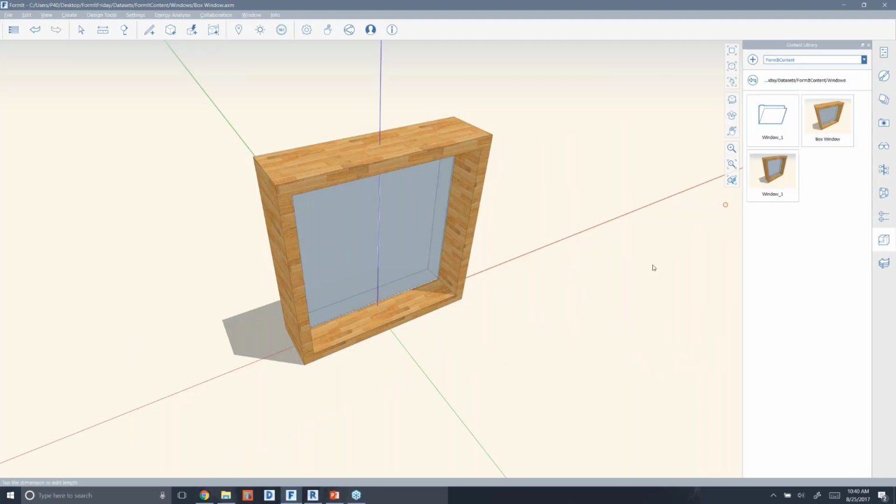And it's looking pretty good. What we realized is that when we were placing it, it did not have the same placement point as what I expected. And I remember why that is. That's because we've got a layer assigned to this object. This object is on the layer window frame 1, which I inherited that information, that metadata, from the previous model. And you need to remove that information from your content. That's part of the cleanup process that we're going to get into next.